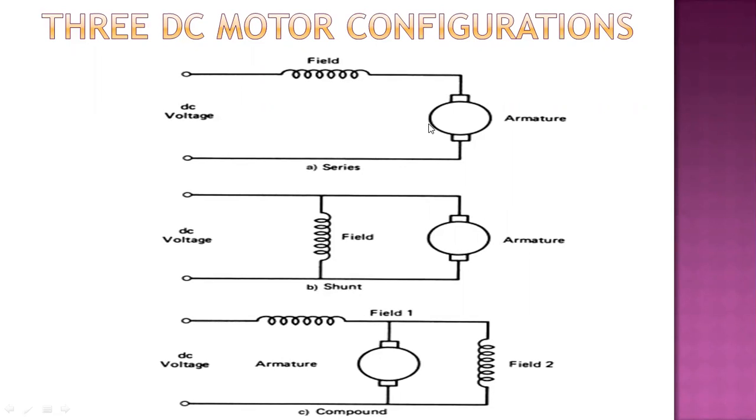So the use of DC motors in control systems ranges from very low energy, delicate control applications to heavy duty control applications in elevators and vehicles also. So in general, the permanent magnet types are used for motors of less than 10 horsepower and wound field types for units up to about 100 to 200 horsepower.